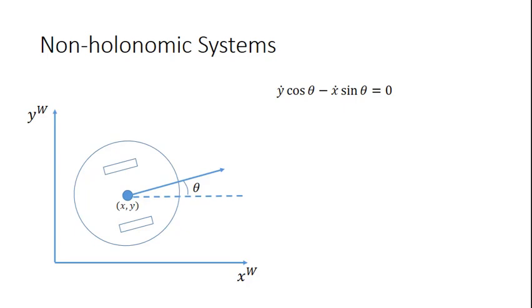This is like the most common non-holonomic motion constraint in robotics. Very often when you're reading about robots, someone will say, oh, I have this car robot, or I have this differential drive robot. It's non-holonomic and it's subject to this constraint. And then it lists this equation here, and this equation encodes how this robot has to move.